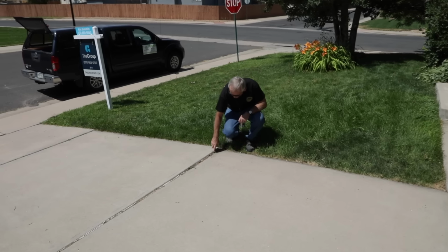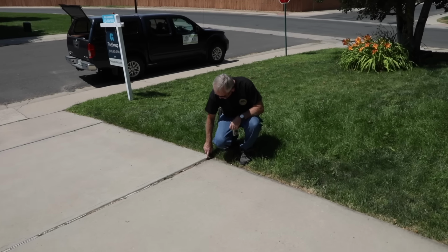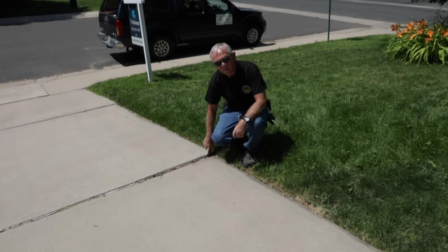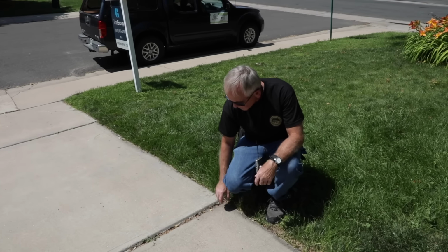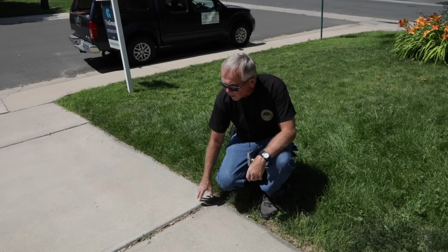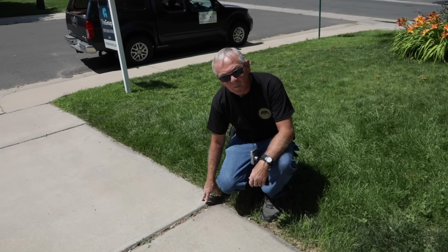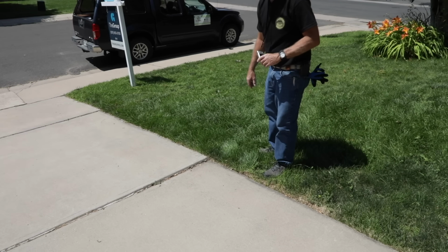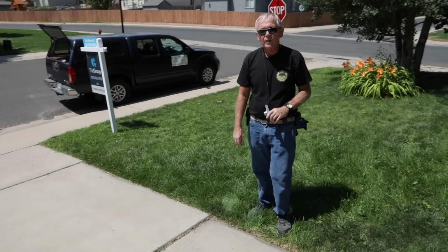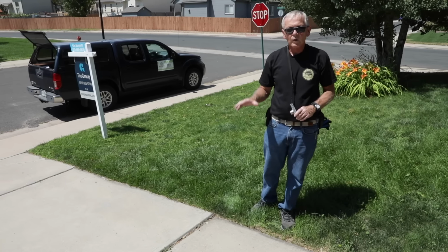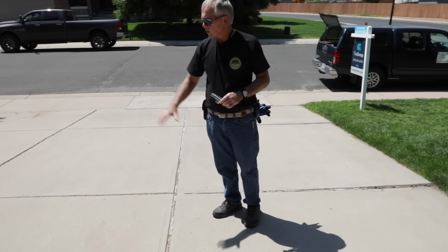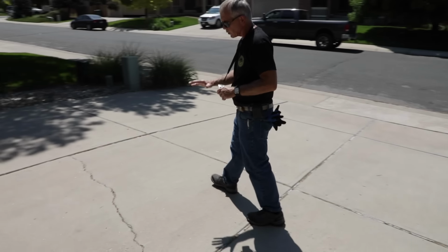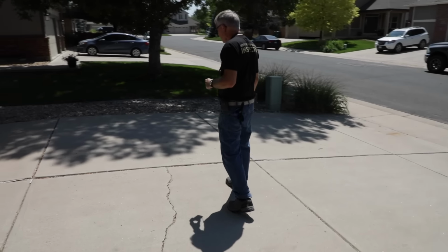So in terms of how much movement, I would say this is probably about 1 inch where this piece here is heaved up from this other surface. So I'm going to note this in my report as a potential trip hazard. In most cases, when you have more than 3/4 of an inch of difference in surface, that can create a trip hazard. Other than that, this driveway looks to be in pretty good shape, other than a little bit of movement and cracking. Pretty typical.